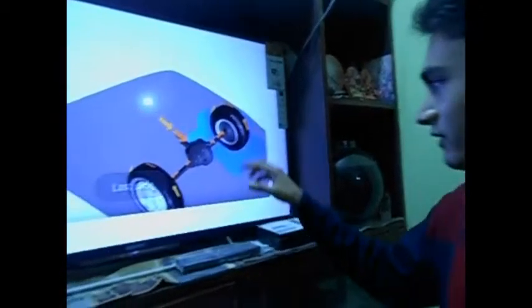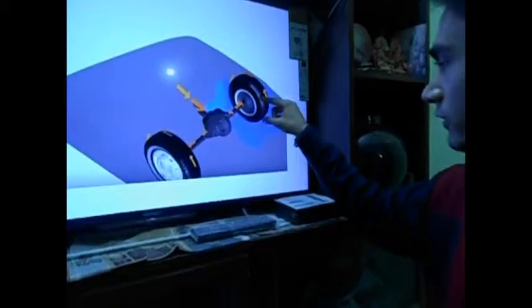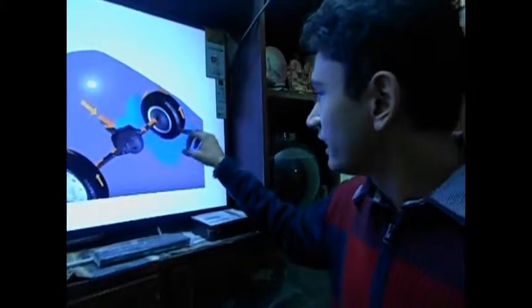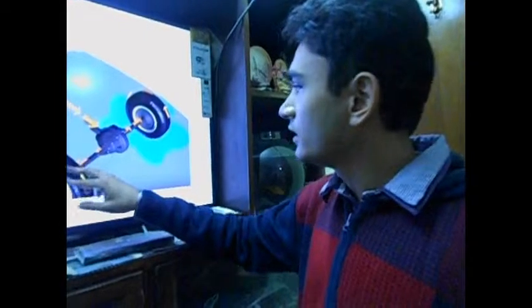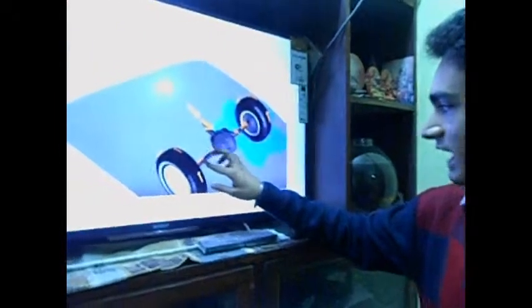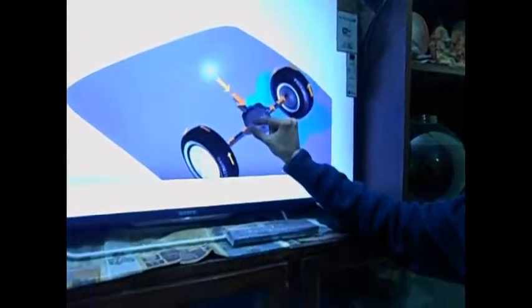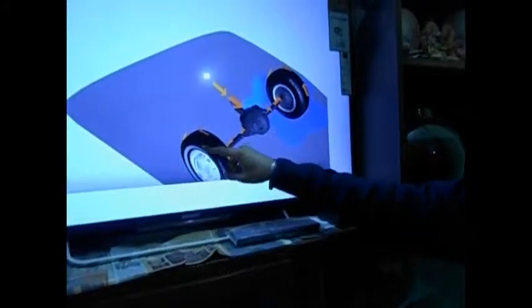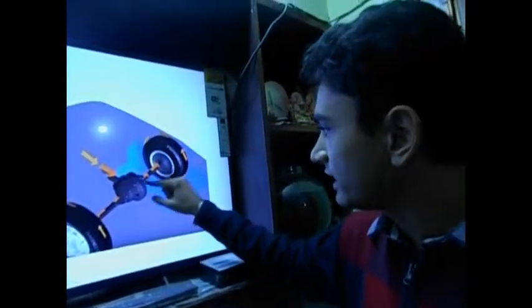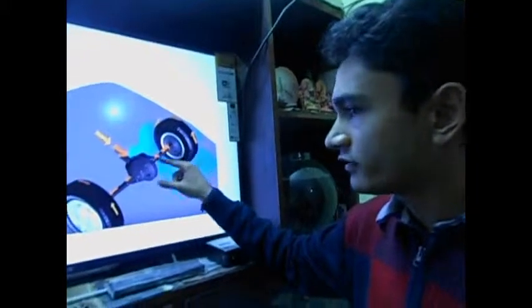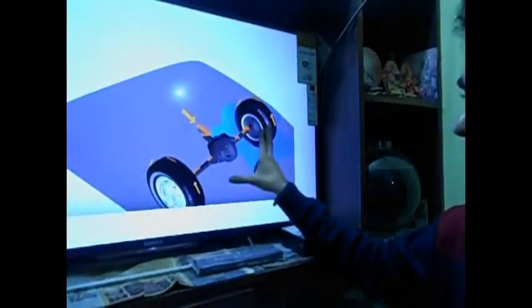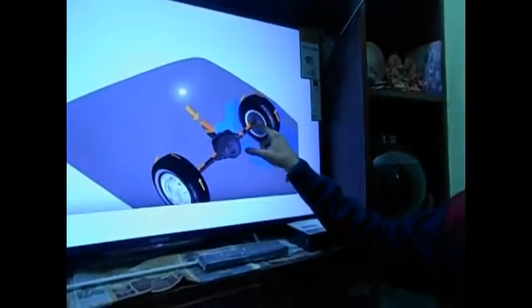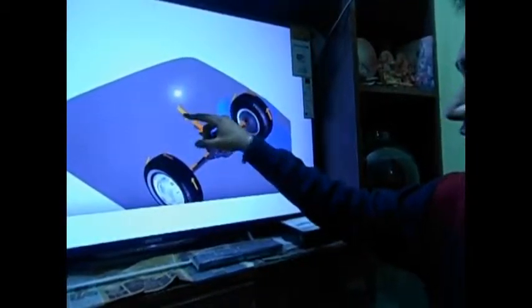This is the situation which I was talking about. On the right hand side, here we have lesser grip, while on the left hand side we have higher grip since it is on the road. If the left hand side provides a reaction, then the left hand side clutch plates will lock together and provide more torque to the left hand side wheel. However, the right hand side offers very low resistance, hence the clutch plates will slip on each other and will not provide enough torque to the right wheel. This overcomes the problem and the vehicle can easily slide over the puddle and move away.